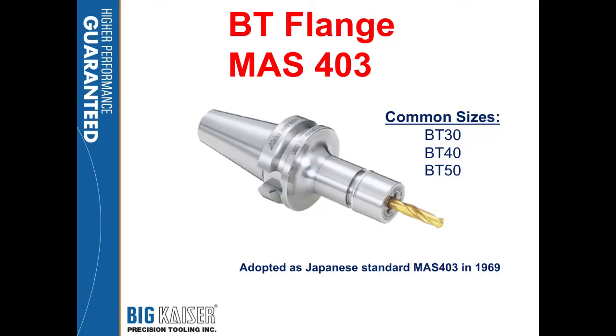So it's about 10-15% of the market over here in the United States. It's not a bad selection to use a BT30 or BT40. There is a commonality to it. You can buy tool holders for it fairly easily. But the BT50 is a little bit out of range for the United States market. Not many tooling companies stock a good supply of varieties of tool holders. If you're buying BT50 with metrics and things that you can get out of Japan or Asia, it's a beautiful way to go.